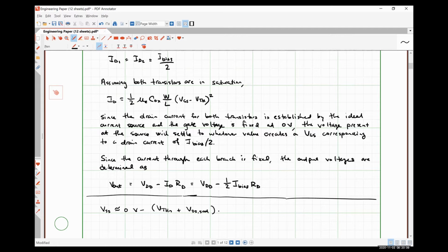So really we are expecting the source voltage to settle on a value where the transistor is just barely in saturation, right? We shouldn't be hitting deep saturation or anything like that. But I'm willing to bet, actually, we'll check that in a second. So this would be approximately equal to negative 0.7 volts plus 0.25 volts, which should give us something in the ballpark of negative 0.95.